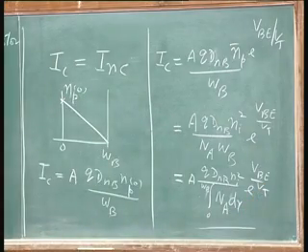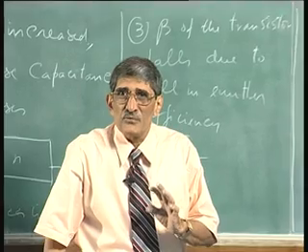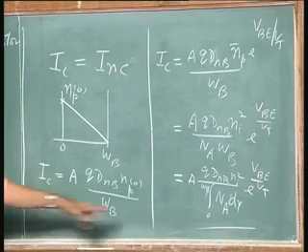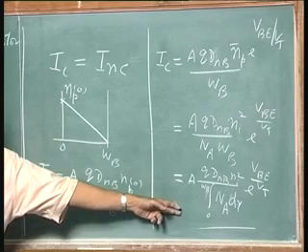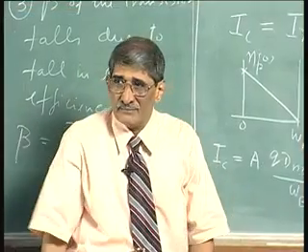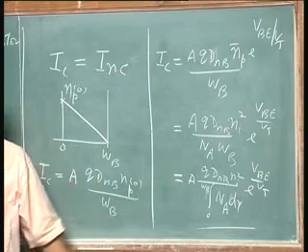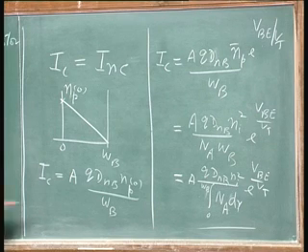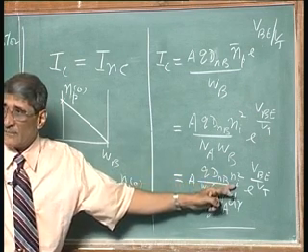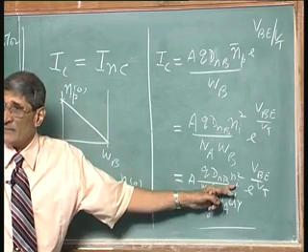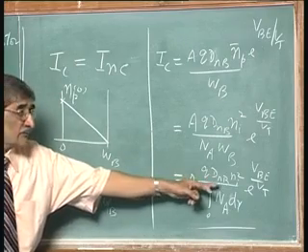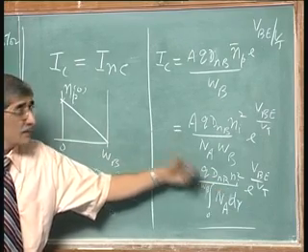Okay, this is just to remind you. You all know it; I am reproducing what we have been discussing earlier in many of the lectures. This is the total integrated doping. I can call it NATB, Na total in the base, the denominator. Please note that the entire thing depends upon Ni square. If I have a device with the same integrated doping concentration and Ni is smaller, that current is smaller.